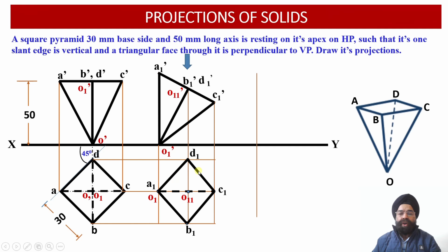Now into this new view, we have to rotate or translate this plan projection view in such a way that the surface O1, A1 and D1 becomes perpendicular to VP. The plan projection view will be reoriented so that this triangular surface, which we visualize using the representation OAD, is located perpendicular to the vertical plane.